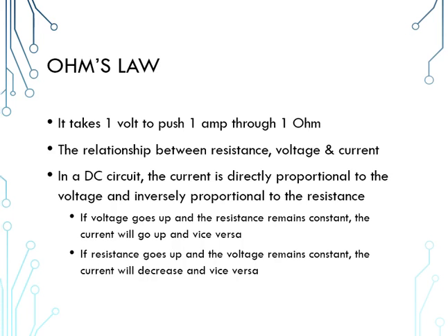Once we measure it, and we can measure our voltage drop across the power source and across the individual component, and we see that we have the right amount of voltage, and we're not getting the work we should be, then we know that our current has dropped, because our current times our voltage gives us our power. And for that current to drop, if the voltage has remained constant, we know we have an increase in resistance somewhere in that circuit causing the problem. That increase in resistance gives us a clue as to some of the places to look in that circuit.